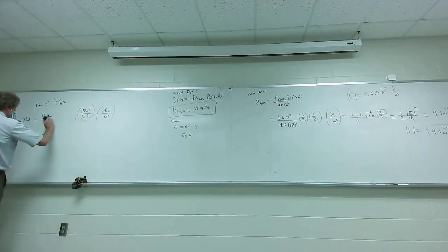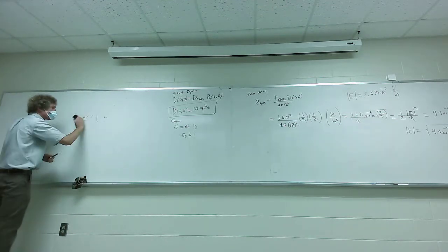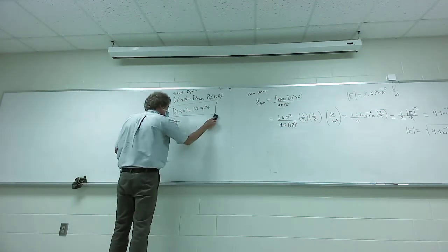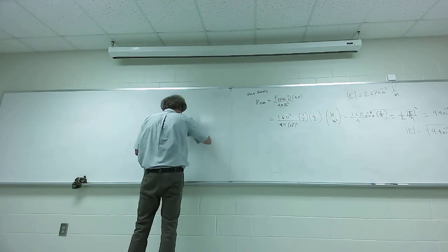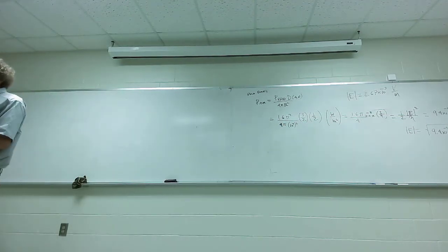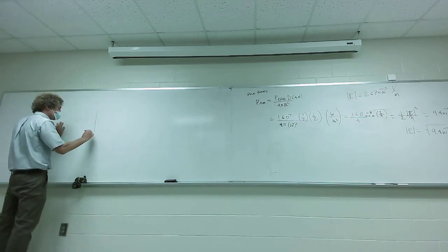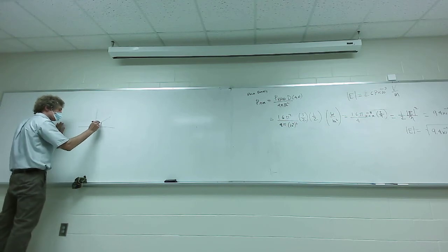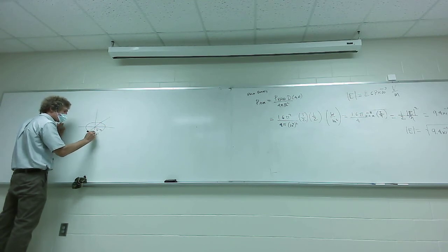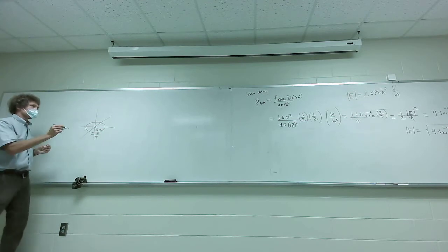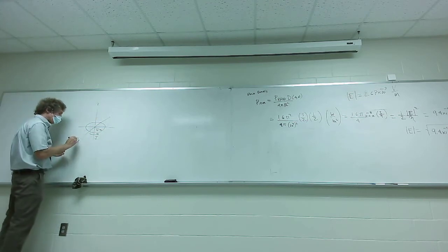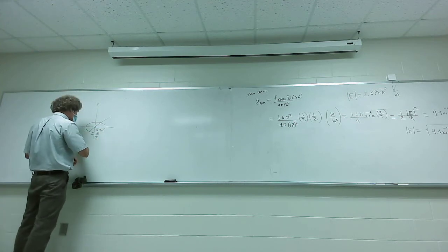That we care about for small dipoles, and that's the loop antenna. Now, this is in your book. Let me just cut to the chase. The loop antenna has the same exact directivity as this one, but it has a different radiation resistance. It's in the book, but I'll explicitly put it down. A small loop antenna centered at the origin will look like this. It will have a radius a, and it will have a current I. In Dr. Whitworth's book, he simply says this is a complicated thing to solve for the actual fields. X, Y, Z.